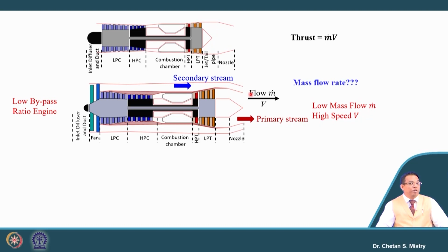So, that is also one of the benefits. Now, the exhaust coming out from the nozzle will have some temperature, and that temperature can easily be identified in terms of IR signature. If we suppress that by using this stream, then it helps. So, that is what attracted attention to using this kind of engine for military purposes. Then people slowly started thinking: can we further increase this mass flow rate?